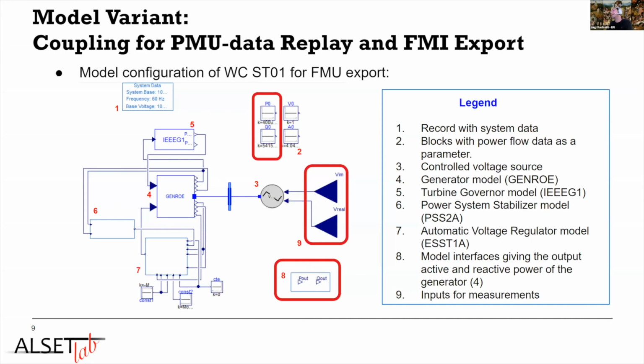The other thing is that in simulation, we compute the steady state. Well, that doesn't exist in reality. There is no steady state. It's moving all the time. So what we do is that we try to calibrate, we try to find a value for the initial power dispatch and the initial voltage that would be required during initialization. But now we have to actually fit it over time, to be able to get a good comparison against the data.